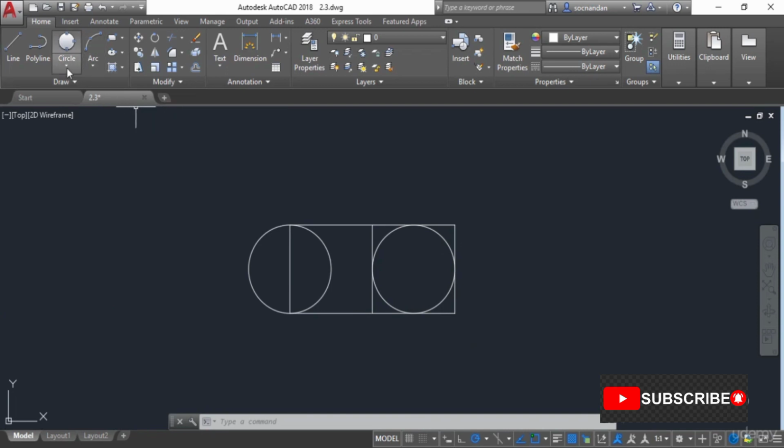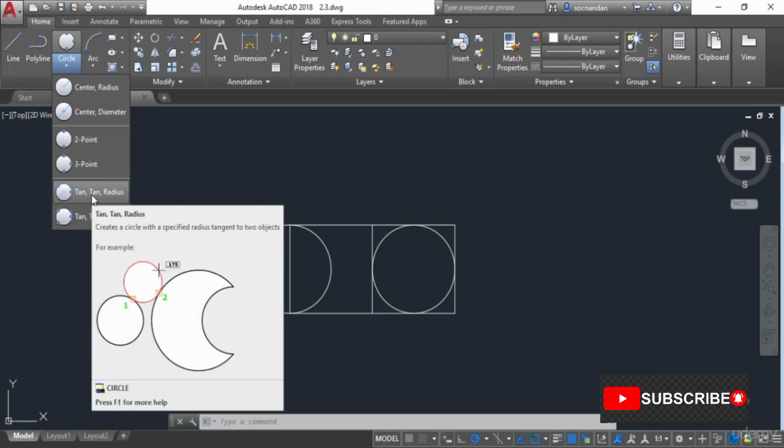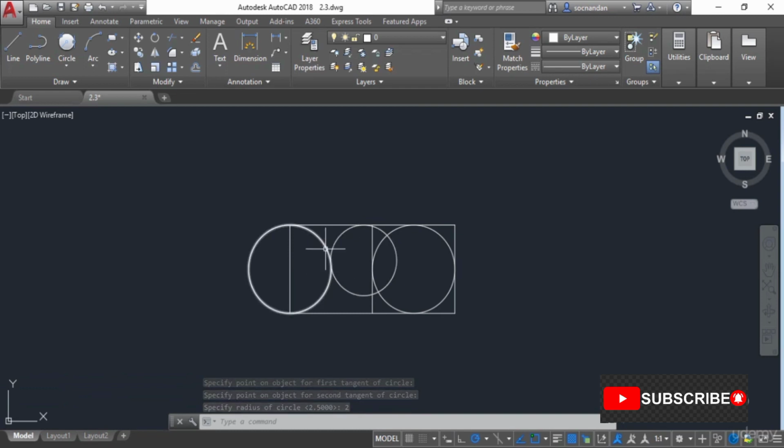Now let's look at the remaining options here. So now we have one more option here, which is tangent radius. So I'll select this tangent radius, and now let's select any of the geometry for the first tangent point. So click on this circle, now click on this line. So now the circle will be tangent on this circle and on this line, and now we need to enter the radius. So you need to enter a radius which will be appropriate for this geometry. So I'll enter 2 here and press enter, and now when you look here, you'll notice that this circle is tangent on this circle, and this circle is also tangent on this line, and the radius of this circle is 2 units.